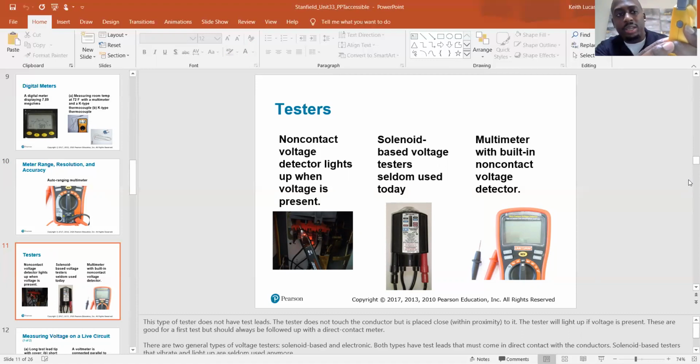and what I'll do is I'll set it to NCV. That NCV section stands for non-contact voltage detection. So now that is set to NCV. If you look at the tip right here, you see those little lightning bolts? That's just letting you know that this is my voltage tester. So I could just point this tip at a receptacle and it'll tell me if it's hot. So I'm gonna point it at my charger and see if it'll beep for me.